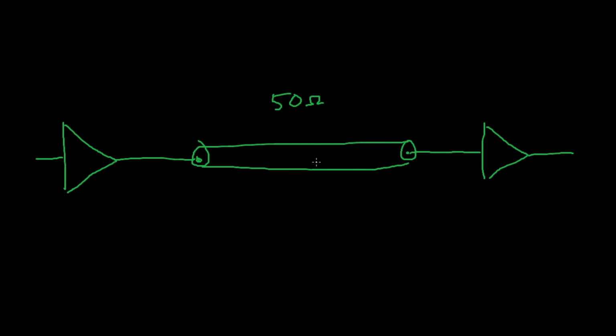So I'm not really going to be able to go into a full explanation of transmission line theory in this video. However, I'm going to try to give you an understanding of what happens with a logic gate whenever you add a transmission line. One of the most important things to consider with a transmission line is its length. If you have a transmission line that's under 15 centimeters, for the most part, you won't see any transmission line effects. Once you start going past 15 centimeters is where you start to see those effects, and there are reasons for that, but again, beyond the scope of this video.